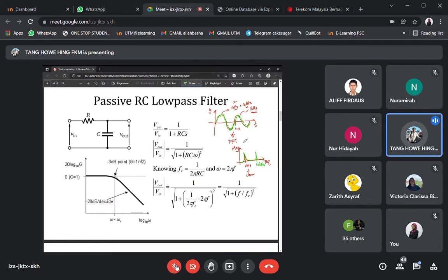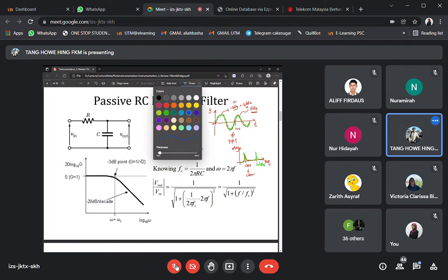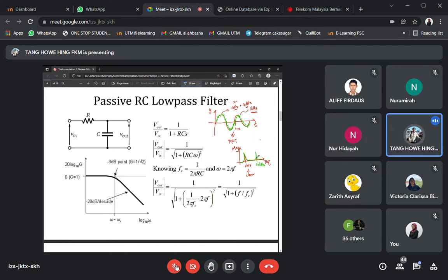Okay, and in this case, we know that 1 kilohertz is the signal that we want to preserve, and then we want to get rid of the noise which is at the 10 kilohertz, and therefore we can actually multiply this FFT, okay, with a window, and this window is, when it is low frequency, extending up to 1 kilohertz, we multiply by a magnitude of 1.